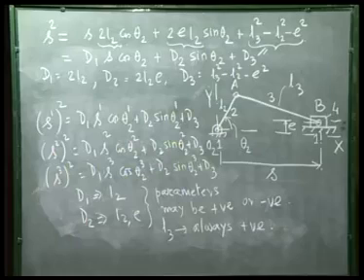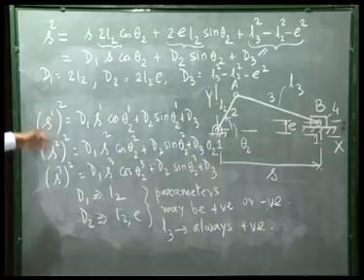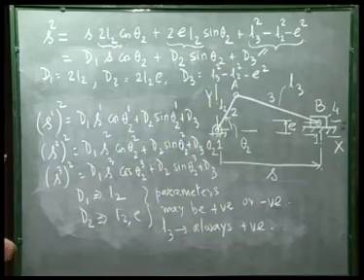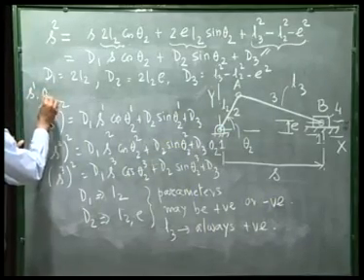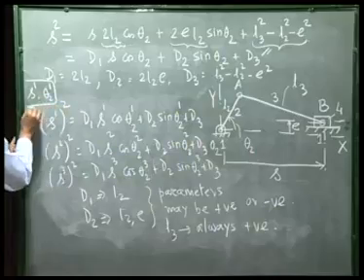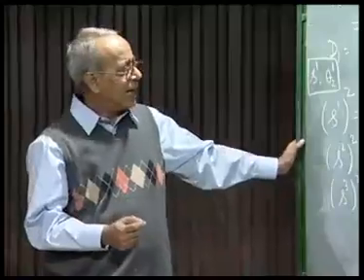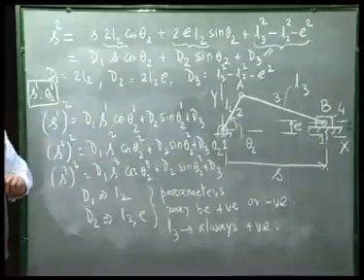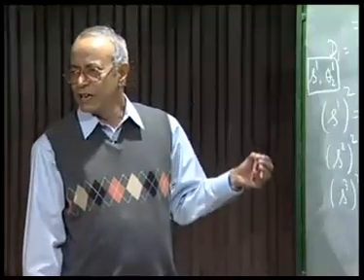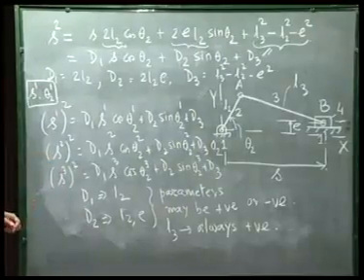The thing to note is that if we want to extend this to 4 position synthesis, that is to generate 3 pairs of coordinated movements, we have to leave either S1 or theta 2 1, which we assumed, one of these two parameters, as an unknown to be determined, and the resulting equations will no longer remain linear in the design variables, and that adds to the difficulty of the solution to this set of nonlinear algebraic equations.